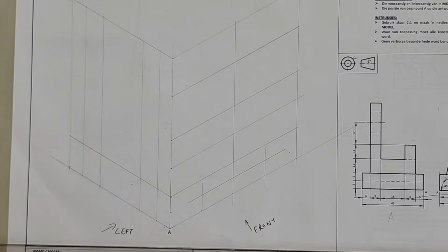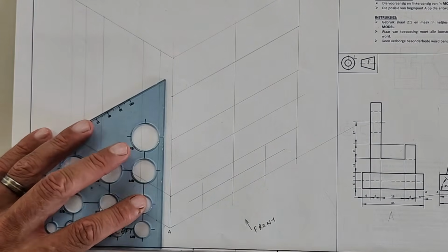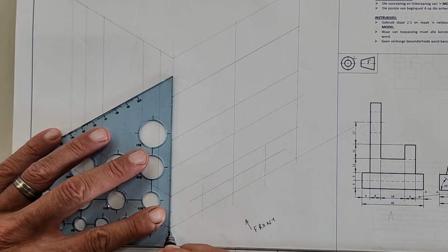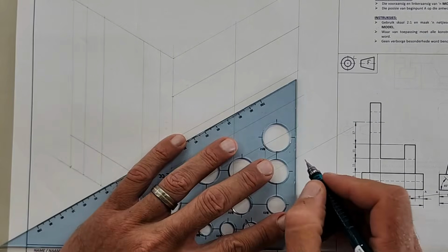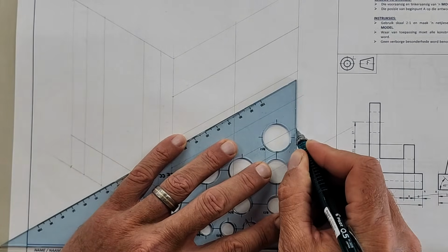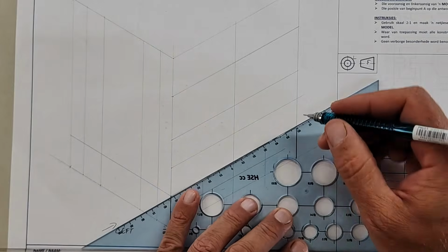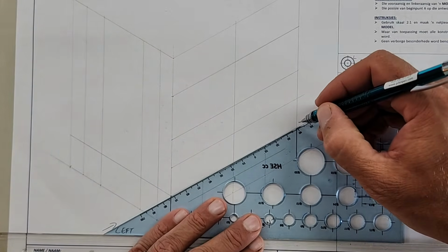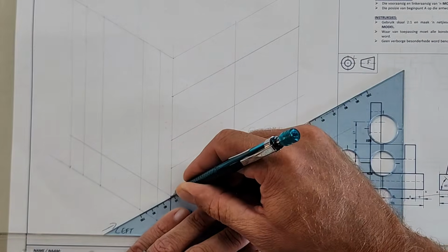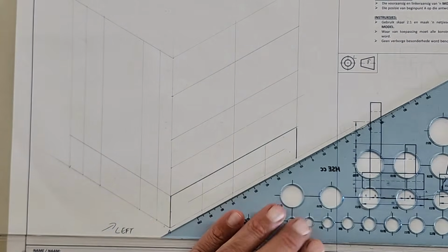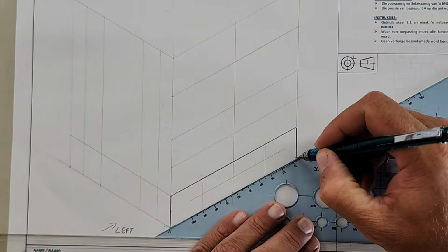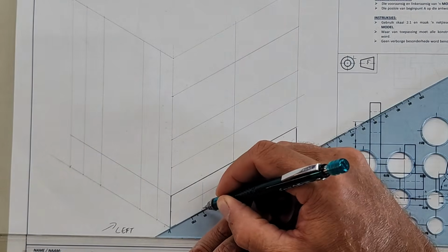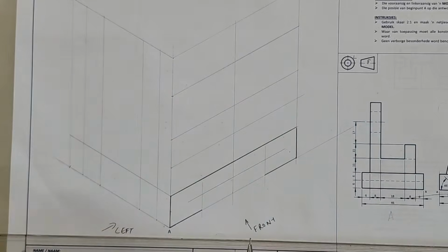Alright, there we go. Once we have the basics, now we can start working on this drawing. Like I've said in previous drawings, I really like to draw what I know for sure right at the beginning, nice and clear. It helps you see the actual drawing much quicker than when it's just a bunch of construction lines. So if you're confident of certain lines, make sure you draw them in. You don't know this angle yet, so I'll leave that out. That's going to be an auxiliary view.